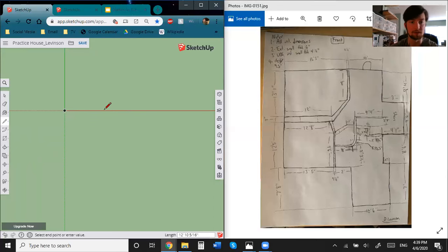Now we'll go over to the right, 16 feet, that's apostrophe, and 3 inches. And you don't have to type anything for inches. So 16 apostrophe 3, did that. Pressed enter. Now we'll go again. I'm defining the wall thickness. I did my best to measure the wall. It was about 4.5 inches.